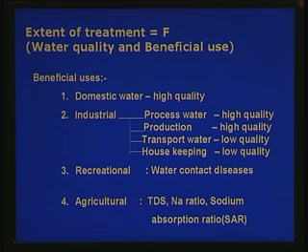One purpose is process water. Process water is the use of water in the process, in the production of a produce. For example, steam generation: I want to generate steam. Steam is generated by using water, and that water should have no hardness, no minerals, and hence I should have a treatment called demineralization. I should remove all minerals from the water for boiler feed purposes.